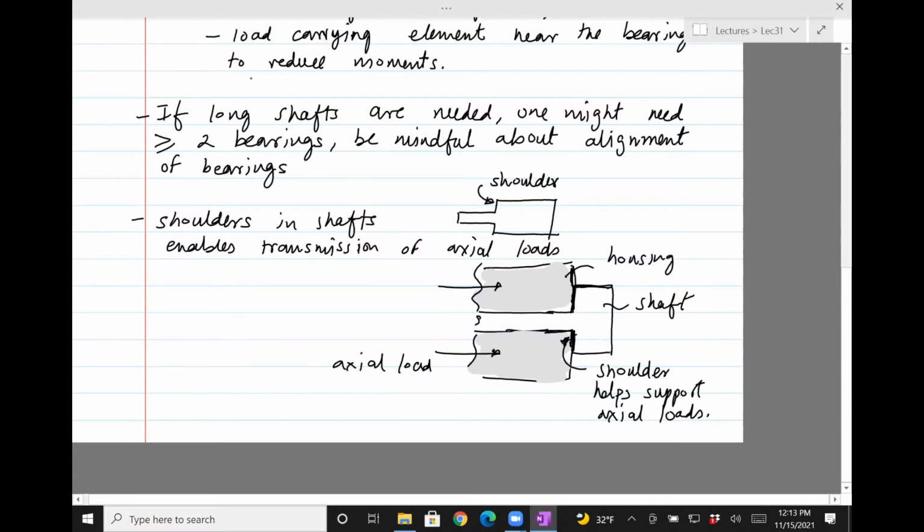So in general, there are many such recommendations, and the way this is done is you want to really think of what you want. Let's say you're designing something and you're in need of A, B, C, D components. Then you want to give a thought. You just go read the book, see what the recommendations are, and then use that. And then each thing you do in this case has pros and cons. For example, simply supported is good, but if you want to have something like belts or chains, simply supported is a bad idea because then it's harder to mount the chains and belts.